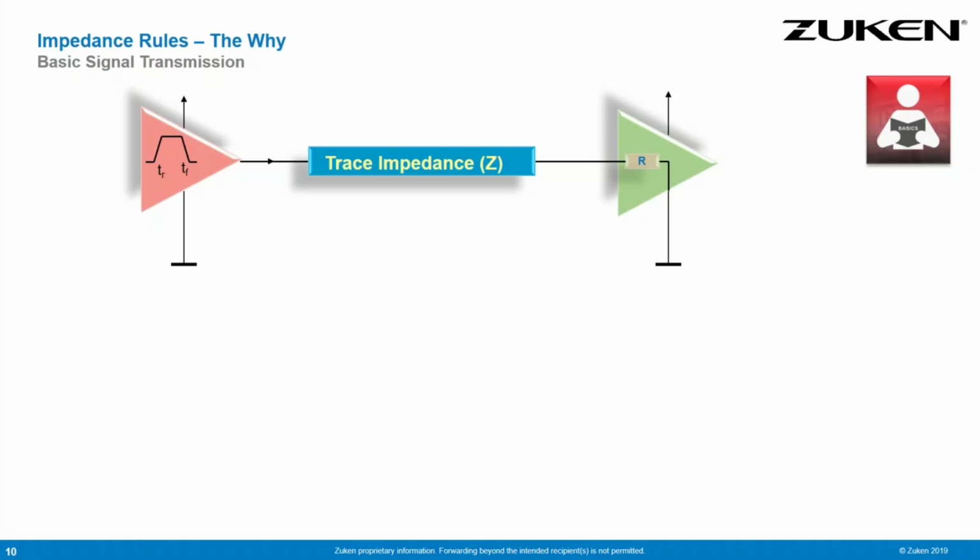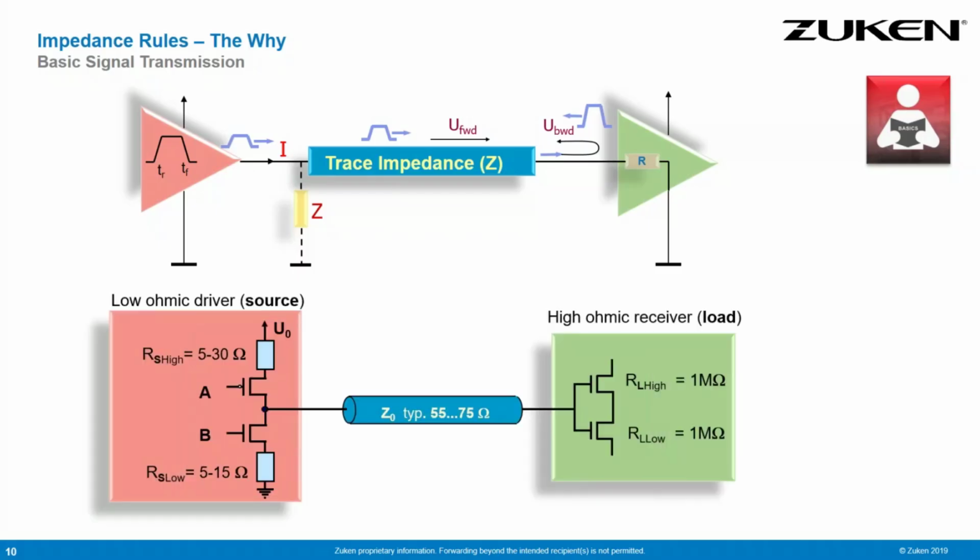And then we have the interconnect structure, which is a trace, which can be more or less simply modeled as an impedance. So it is a kind of resistor. We have this kind of artificial resistor, which shows up as energy is traveling from driver to receiver. The energy, the voltage, is traveling along the trace. And then the signal arrives at the receiver. Then part of the energy is reflected back, so we have energy traveling back on the trace. This energy will harm a signal which occurs from the next transition. So the next signal will see a voltage impacting the shape of the signal. This is causing this kind of degradation.